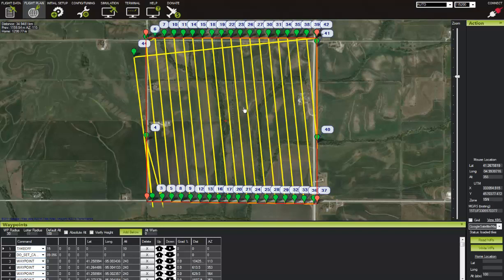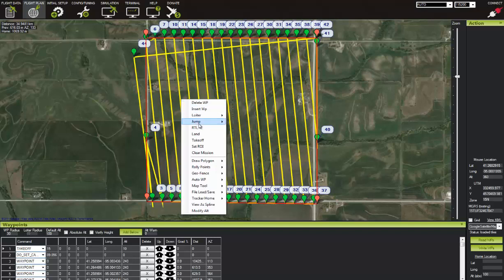Another couple of options that may be useful to you as you learn how to fly is return to landing. Anytime you choose this setting while flying, the UAV will abort its pre-programmed mission and fly back to the takeoff point or initial UAV sync point. You can also do a few other things here.